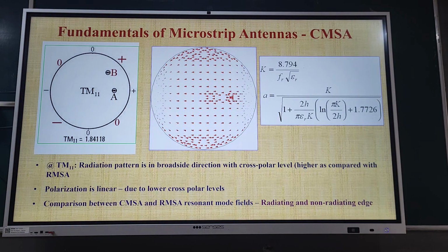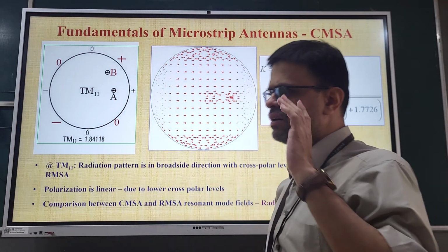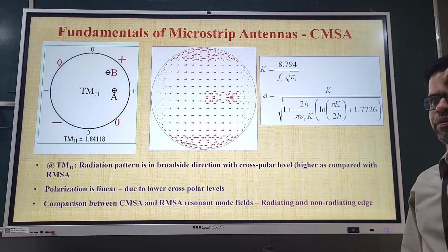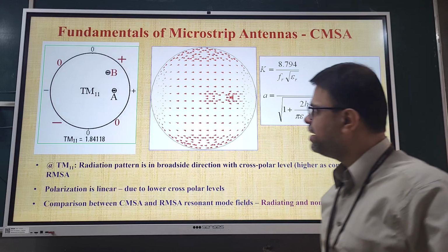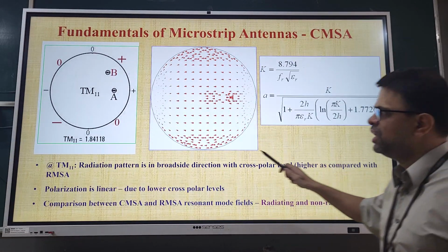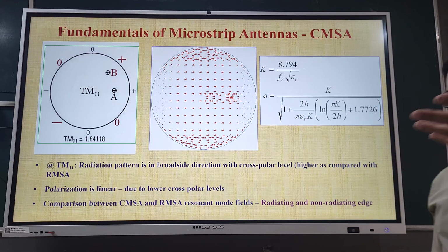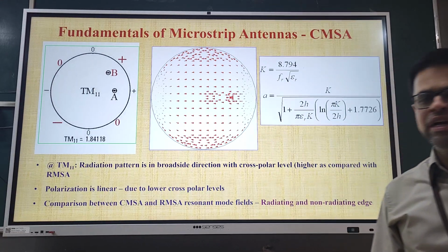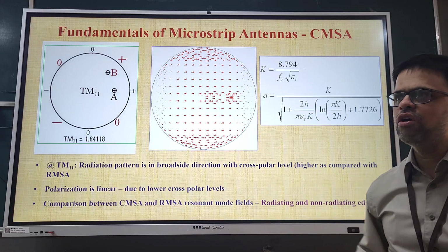Now just to have a continuation, these are the details related to the circular geometry. I'll just touch upon one particular point which we have not discussed in the topic when we discussed about the basic. We have said that one mode, which is a fundamental mode in circular patch, it will get excited when the feed point is over there. What will happen if the feed point is offset? If you apply an offset feed point, that is neither along length, neither along width.